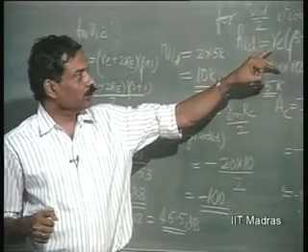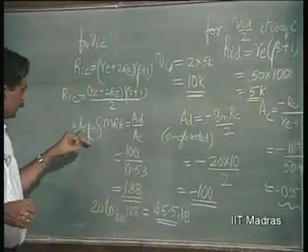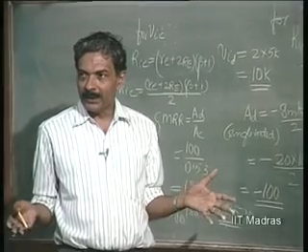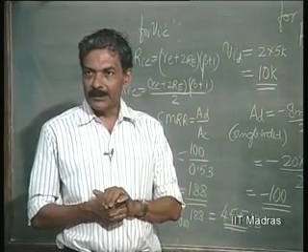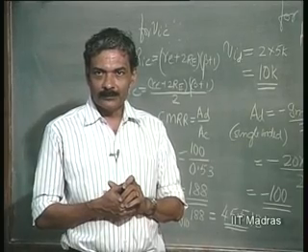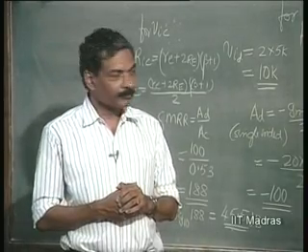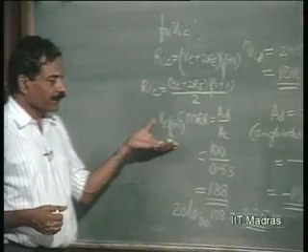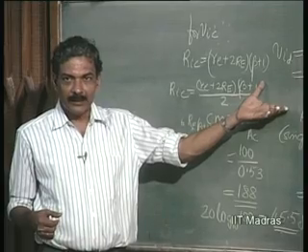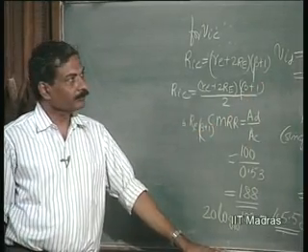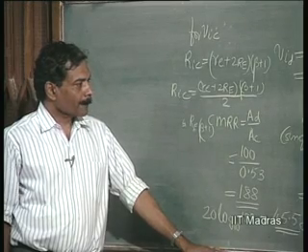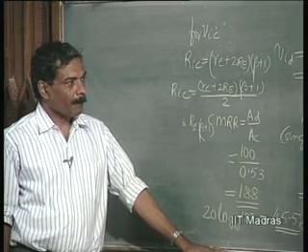This impedance is 2 RE into beta plus 1. This is RE into beta plus 1. So, it is RE by 2 RE. Again, it is going to be your GM into RC by 2, GM into RE by 2. So, this factor also gives you a measure of what? Your common mode rejection ratio. Is this clear? So, this completes the problem.